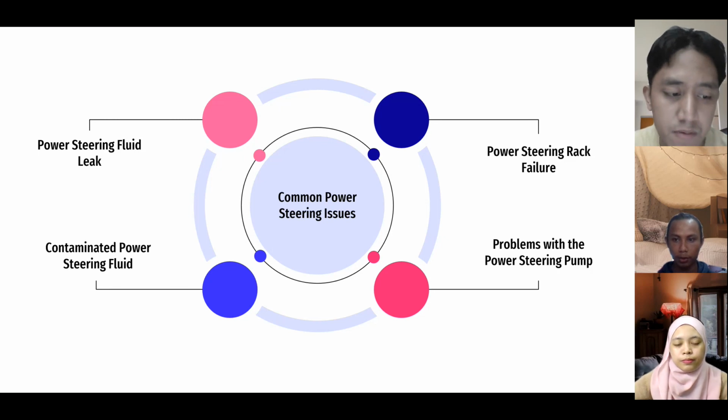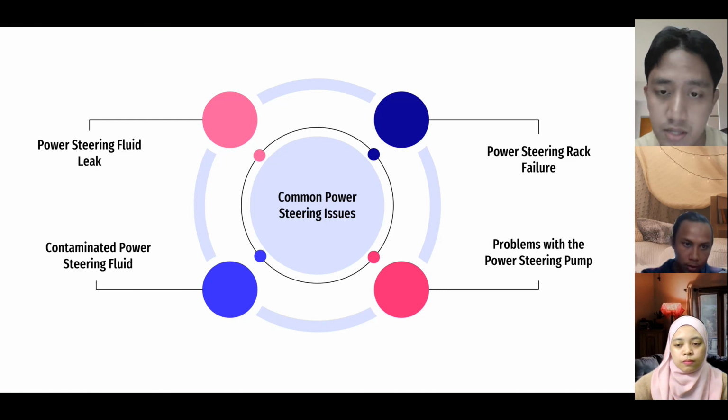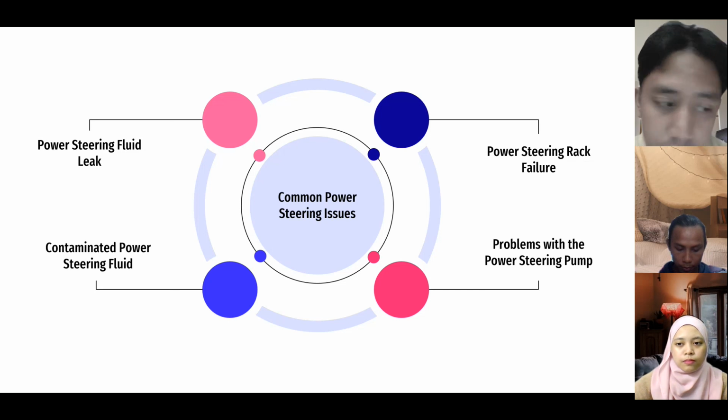The power steering pump is driven by the engine of the vehicle. A belt connects the crankshaft to the power steering pump, and that belt can wear down, fracture, and finally break over time. Power steering will not work if the power steering belt breaks. Inspecting the belt for signs of wear and determining if it needs to be replaced should be part of a car's normal maintenance.